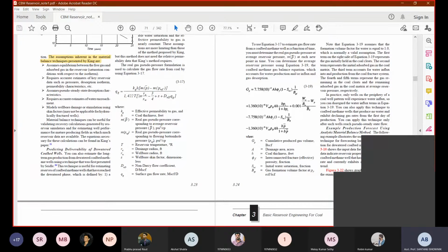This damages the created fractures, depending on the actual cemented surface in the real case which is created. This is called the skin factor. The more damage or the more incremental skin fracture is obviously something we don't want, because in that case our gases will escape into the side directions.